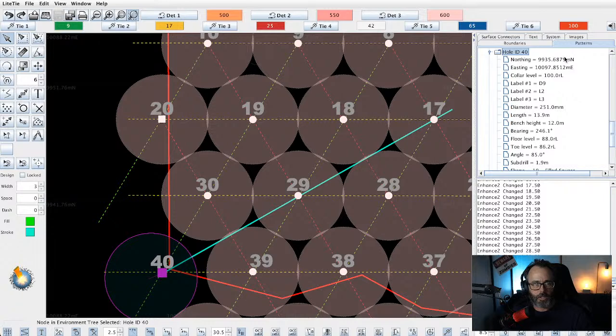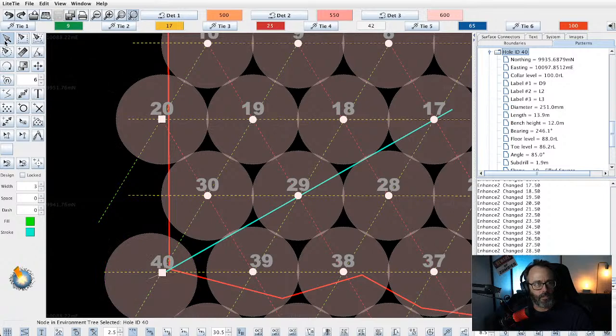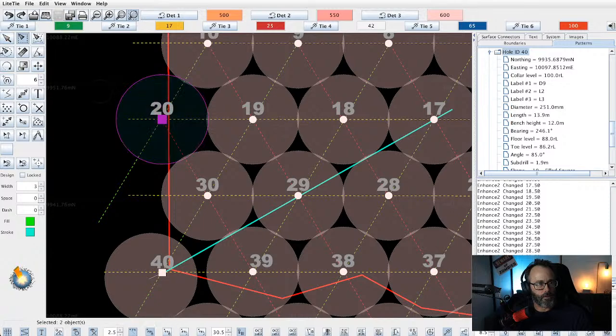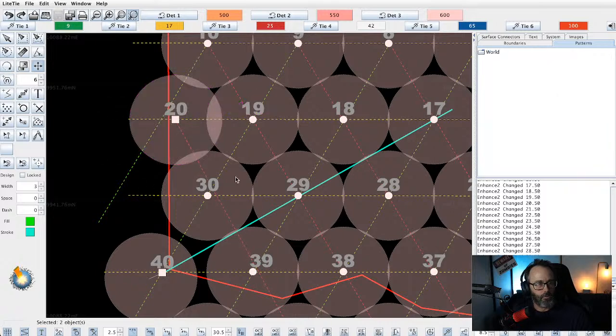And we can nudge it up or nudge it across, but I've already moved it and messed it up with all these lines, so we'll pick another blast hole to move, and I'll make sure that I can select only the holes. Yep, selecting only the hole, and then selecting the move tool, and now I can shift it across. Well, there you go, it's grabbed that line again. But you can see here the intent with all this gridding is that you can now see where the toe should be. So at that point you can now influence the angle and dip.